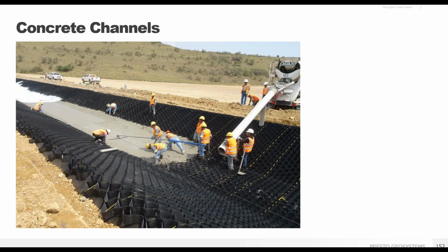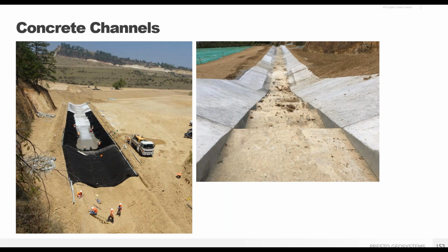If you have high flow or shear stresses for your channel armoring, you may likely be using a concrete infill for your GeoWeb channel, like this mine closure channel in Guatemala. Here we see the technique tip of filling the channel bottom first, then the side slopes. This is to ensure the system stays in place as no stakes are used, but also facilitates construction, as crews can traverse the channel bottom as they finish the side slopes. Again, for the side slopes, fill from crest to toe.